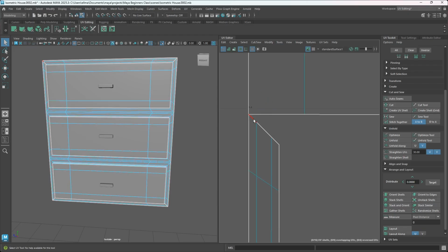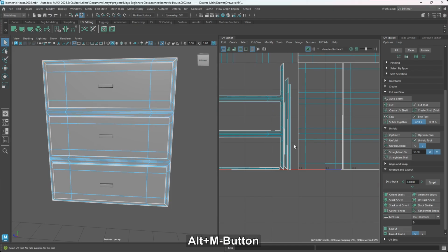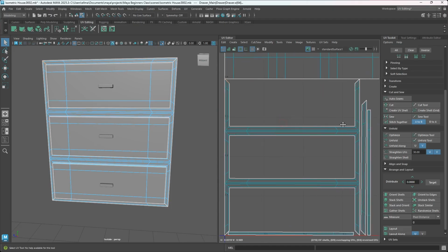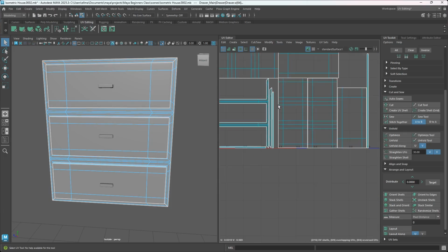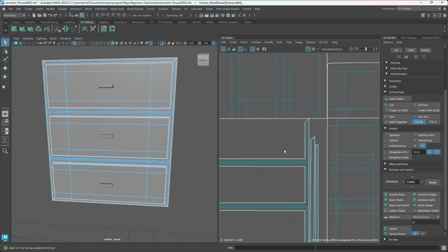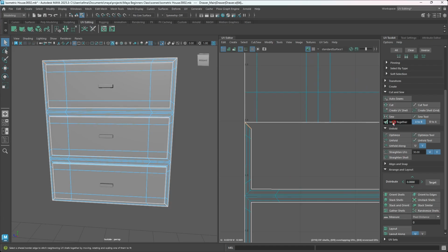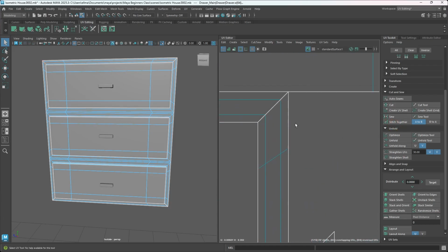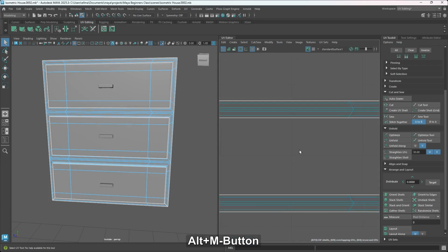Okay, now we can just go into the edge mode, select 1, 2, 3, and let's see where it selects. Did it select any other part? And of course it should. So let's see. Yeah, it's selected here. So now we can just stitch together, and I think we need to stitch this one to stitch together. All right, that is fine.